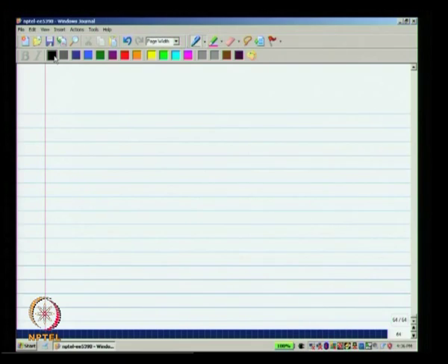First of all, you can look at the loop gain and use the Nyquist plot to find the stability, and in most practical cases you do not have to draw the Nyquist plot, you can simply look at the Bode plot and ascertain stability. And we see that only around the unity gain frequency it has to have a 20 dB per decade slope. So, the circuit that I am going to discuss now also illustrates this in a slightly different way.